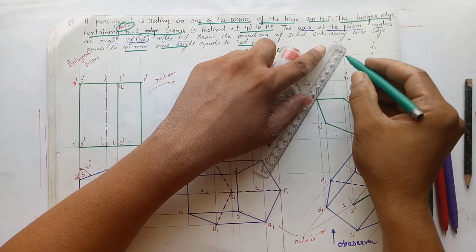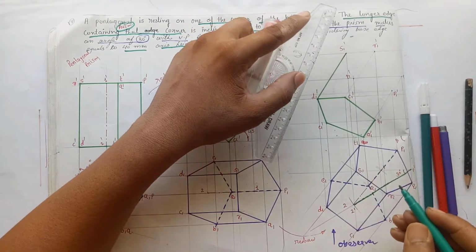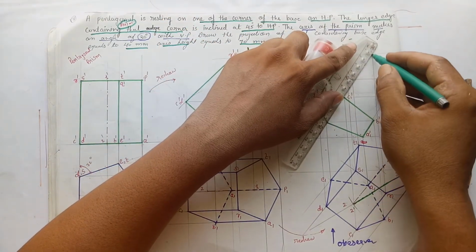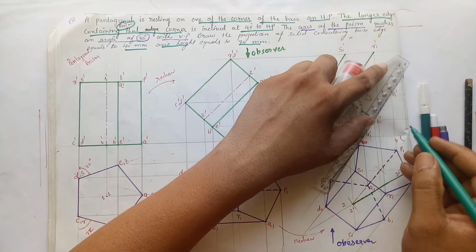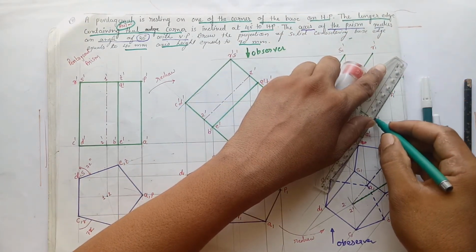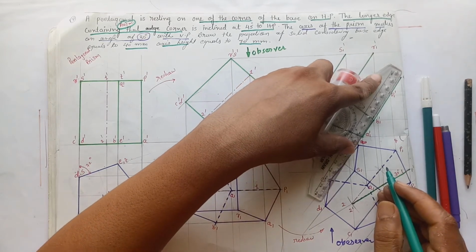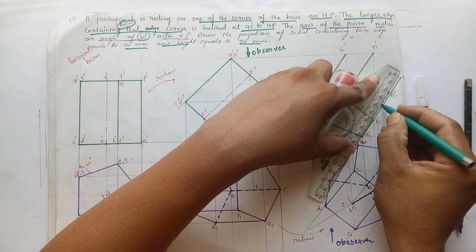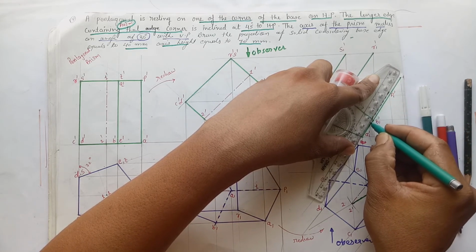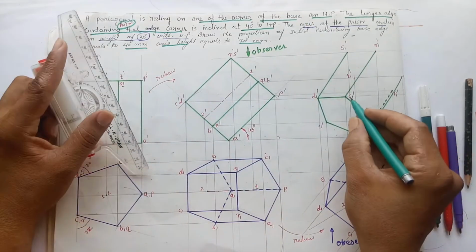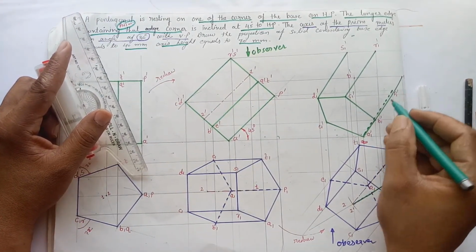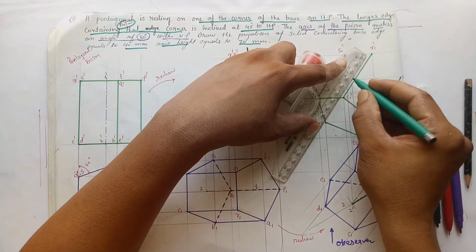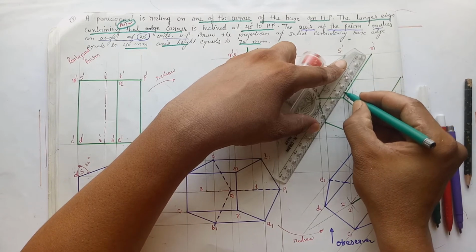you have to apply the rule of intersection of the visible outlines and hidden outlines. So this edge is going to be visible due to no intersection in between T1 S1, no intersection between C1 R1, no intersection between B1 Q1. But now A1 P1 is going to be hidden because of intersection, because A1 P1 side edges intersect at C1 B1, so it is going to be hidden, and E1 T1 is also going to be hidden.